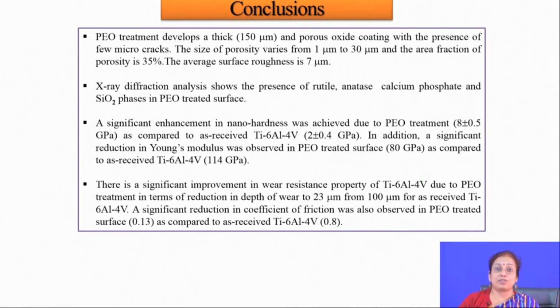So, the roughness is because of porosity. Roughness is beneficial for some properties like biocompatibility and wettability. So, this is another uniqueness of this particular process. The third uniqueness is that in anodizing, the surface is full of oxide layer and that is monolithic, but here the thick oxide layer is still not really so brittle because it is composite in nature.